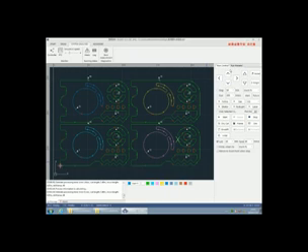Six, operate the cutting machine. Before we click Start button to cut, there are a few more things we might be interested in. Under the Run Control section, we can test if the head follows directly, if the gas and the laser work properly. And we can also go frame before cutting.